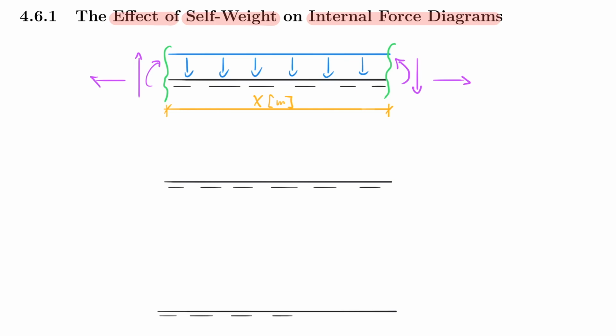And what we have to understand here to extrapolate our understanding from these pictures later on is that, of course, this is cut away as well. And so these beams are just x long as well. And what that means is that I do not know exactly what value I will have at this location, right? So I will just think about what impact this force will have. And keep in mind, we call this force usually W, and usually that's given in force per distance. And so we need to think about what that means.